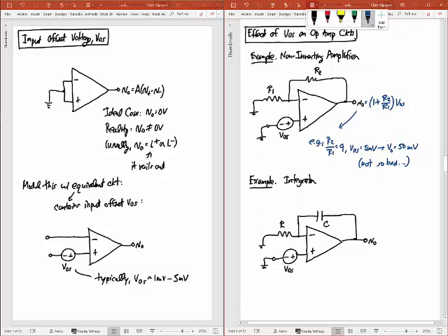But if I take a look at this integrator, what I've effectively done was, because this op-amp is ideal in all respects. Okay, and so that's how we deal with non-idealities, right? We take the op-amp, we assume it's ideal, we add things around it. So this VOS is modeling the non-ideality. The op-amp we still assume is ideal. Okay, that's an important point, right?